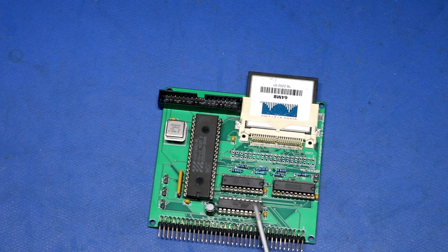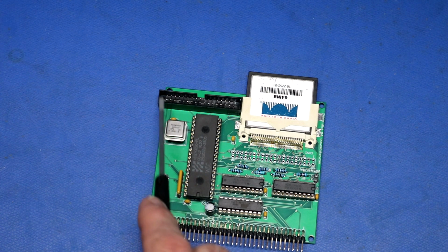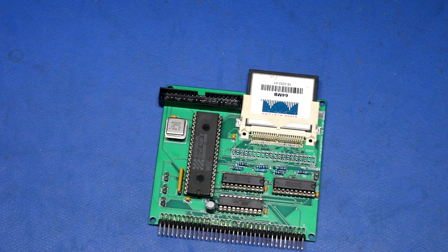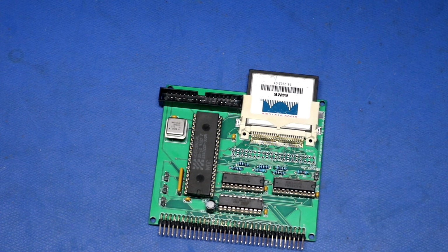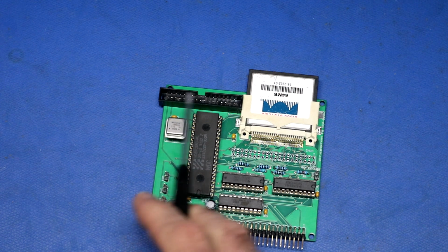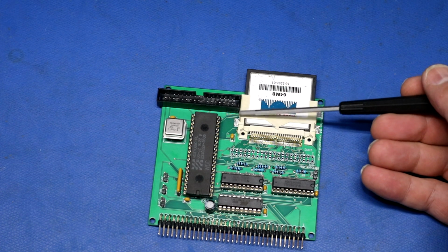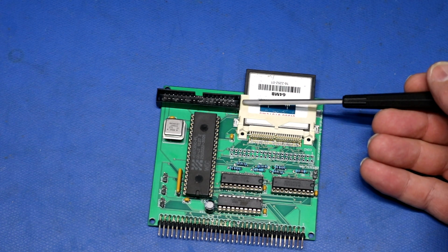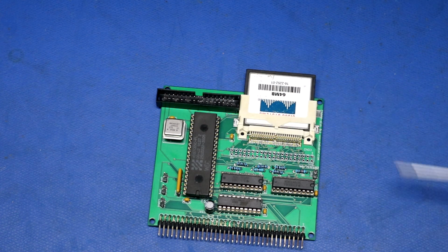I did use the PLD right there to do its address decode and a few other things like that. There's its pull-up resistor and its crystal. And it has a 34-pin header for your floppy cable to plug in. Some jumpers for some various options that we don't really need. Now, this did get a little bit close, these two connectors, and I actually had to snip a little bit of the plastic off this shrouded header to get it to fit next to the CompactFlash. I might try to see if I can move something a little bit on the next respin of the board so they're not so tight.